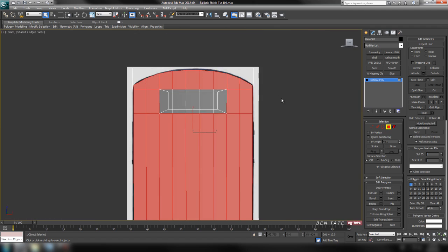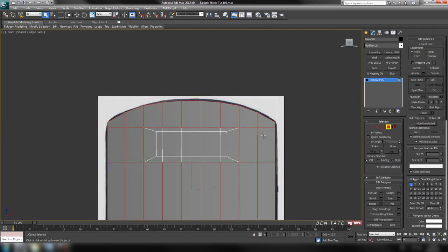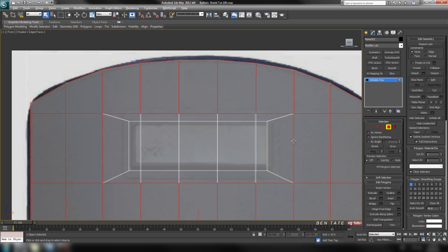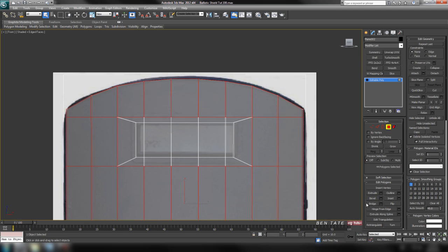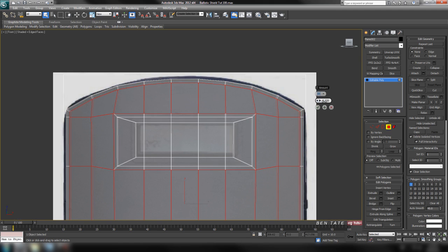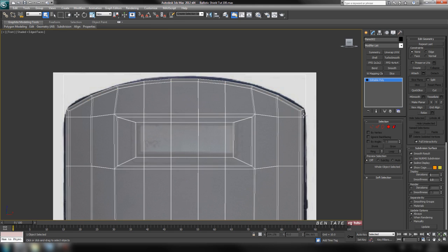And we'll just do an inset on this. I'm just going to turn off my polygon shading with F2 in the front view. And we'll toggle see-through again. And let's just inset these now. Okay, we'll just take it up a little bit here. It doesn't have to be a lot. Let's do maybe around 6.5. And we'll hit OK to that and get a polygon.